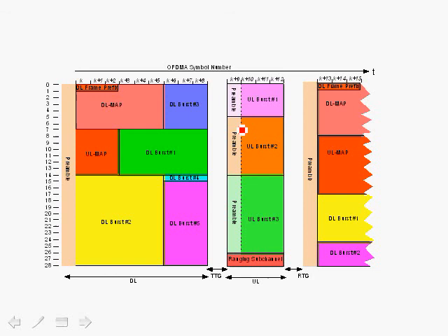So each subscriber will have a different allocation because it has a different data burst, which is described by its allocation in terms of its subchannel offset, number of subchannels, and time slot offset, and the number of time slots, for example. So this subscriber would have to allocate its own pilots that change depending on its data burst. So that's the issue that we want to deal with, and the other issue that we want to talk about is that the